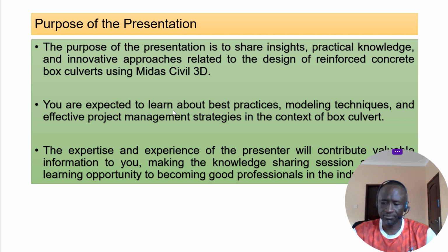I remember last time when we started, we were hinting on reinforced concrete. I think we handled slab bridge. I know after this box culvert, we shall move to at least concrete girder. I think the concrete girder will be first when it is propped, within 15 meters, and then we shall also do the one that is not propped. You precast in the yard, and then you lift, and then you cast fresh concrete and allow it to set, and then you load, which has construction stage loading. So that will be what we shall be doing after this stage.